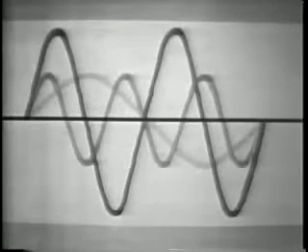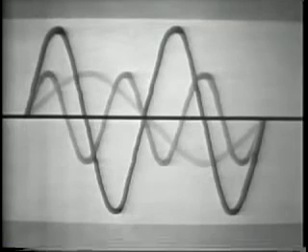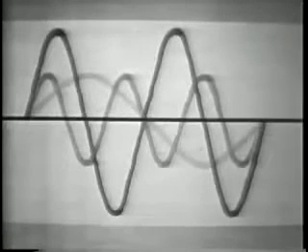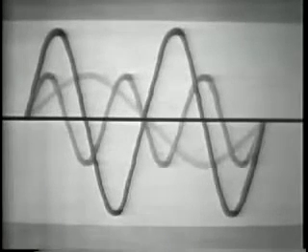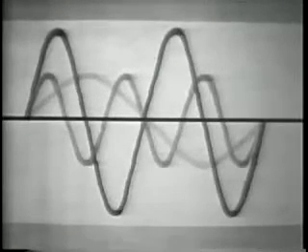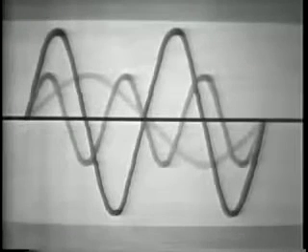Because what you see on a scope is not just the carrier, the sidebands are also present. To show the carrier by itself, while the sidebands were present, the display would have to look like this, showing all three frequencies in their individual forms and relationships simultaneously. But as you know, a scope cannot show three different voltage values simultaneously.